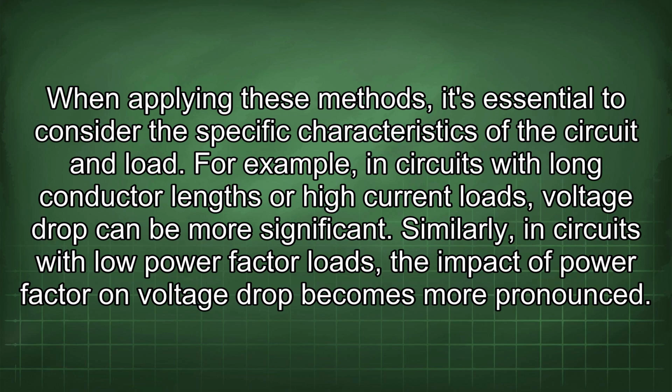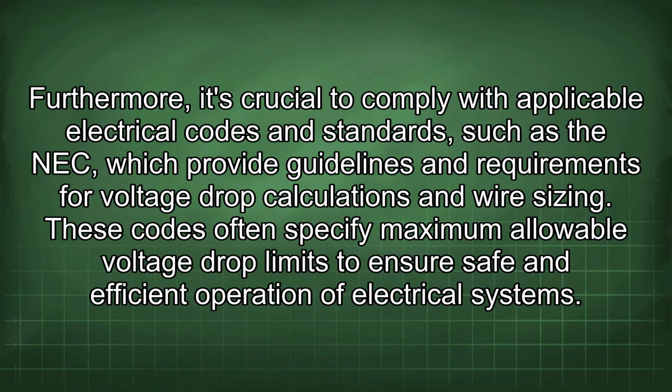When applying these methods, it's essential to consider the specific characteristics of the circuit and load. For example, in circuits with long conductor lengths or high current loads, voltage drop can be more significant. Similarly, in circuits with low power factor loads, the impact of power factor on voltage drop becomes more pronounced. Furthermore, it's crucial to comply with applicable electrical codes and standards such as the NEC, which provide guidelines and requirements for voltage drop calculations and wire sizing. These codes often specify maximum allowable voltage drop limits to ensure safe and efficient operation of electrical systems.